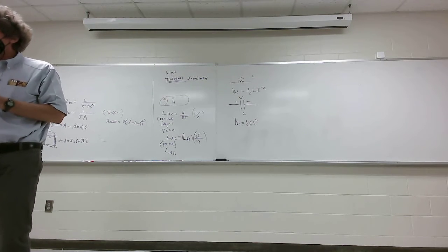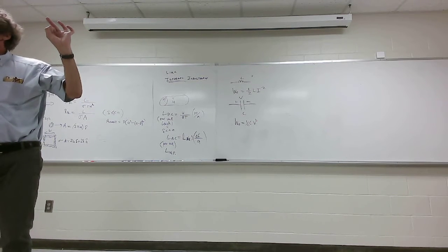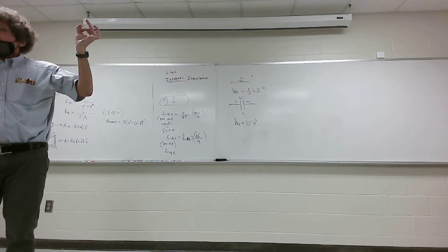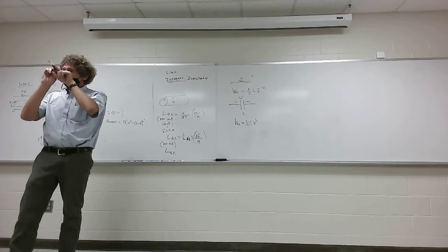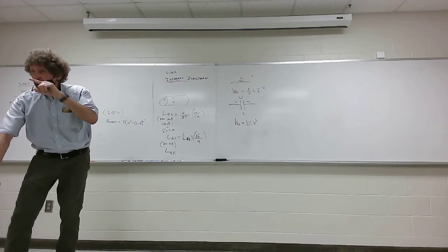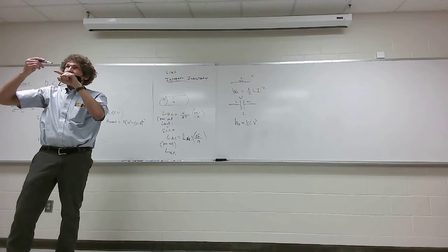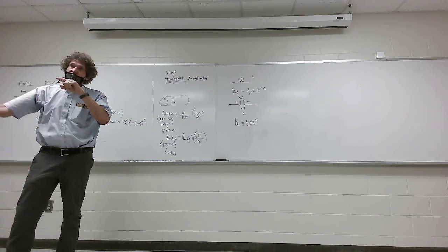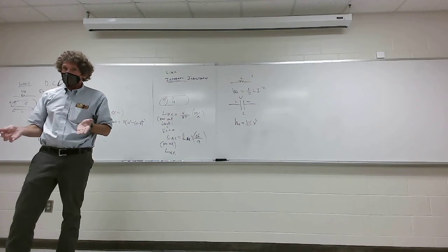It's all contained within. Then the internal inductance of your core is pretty much the internal inductance there and the energy inside it. That's it. But if you have 2 wires, now think about this. You're used to seeing extension cords and stuff, right? What if I have a wire like this that goes down to the back wall, comes up and goes this way here? Now I have this giant cross-sectional area where the actual magnetic flux will go, and there will be a large amount of energy outside that circuit.